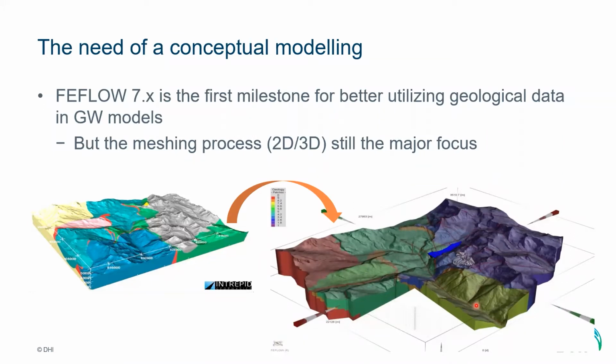Normally you apply a lot of effort to set up your 3D geology, and you need to migrate this into FEFLOW, into a groundwater or hydrogeological model. Sometimes you need to simplify the numerical model because of the mesh or because of other types of processes. So we created a workflow to import meshes and also to generate a mesh using 3D geological information. Of course, there are some bottlenecks, as everyone here will know, but that's the intention.